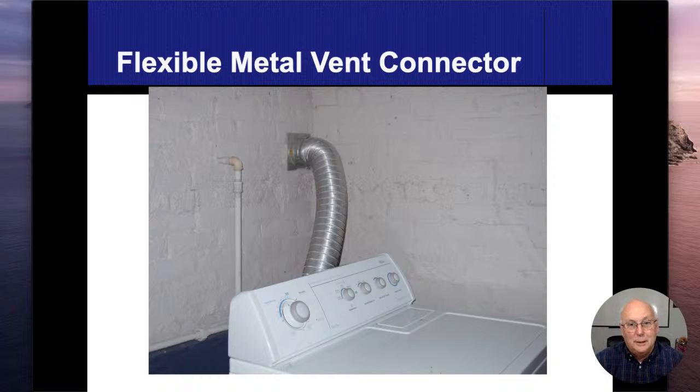I'm not a fan of cleaning the vent connectors. And you know what? I'm using the term vent connector and I'm using it wrong. These are called transition vents. These are also not allowed to go through the structure or through a floor. Typically, I believe they're 6 feet max in length. But the dryer vents, which are smooth wall, some dryer companies say you can go up to 50 feet on the smooth wall ones, but not with these things.